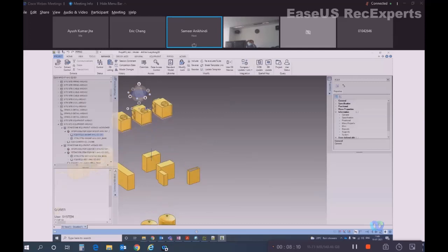Now let me show you another thing in this input ribbon. So input is being asked in form of easting, northing and elevation, E, N and U. What if you want a polar coordinate system? Polar coordinate, as you know, asks for distance, radius and angle. Sorry, you have to use this key. So below the escape, there's a tilt key. Below the escape button, there's a tilt key.